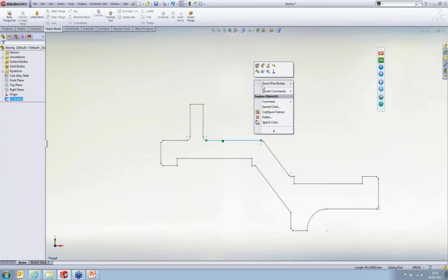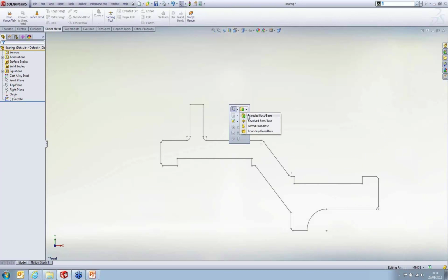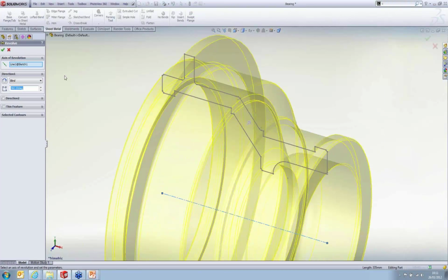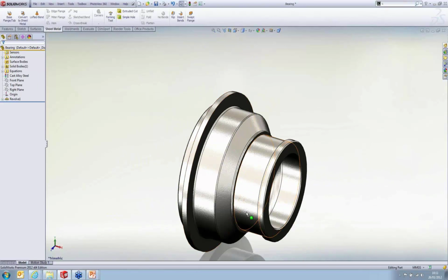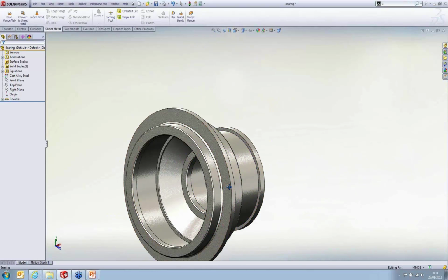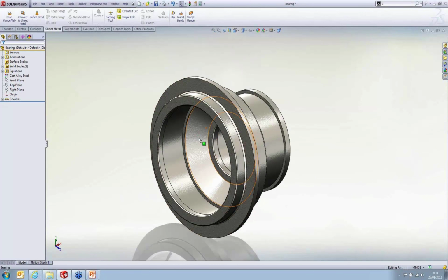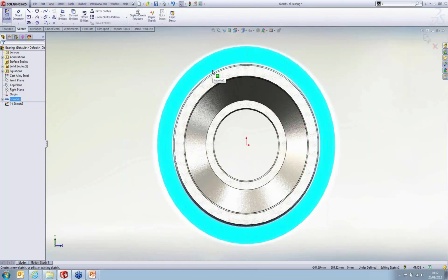If we just go ahead now and revolve this component, we'll take a look at one of the other changes. And again, this is a nice productivity gain. It's a system option, so you can turn this on or off as you require. But I can now set this system option so that when I start a sketch, it automatically orientates me normal to that sketch. So instead of me having to press normal to or navigate around the model, it will automatically do that, as it does anyway for the first sketch in a component.